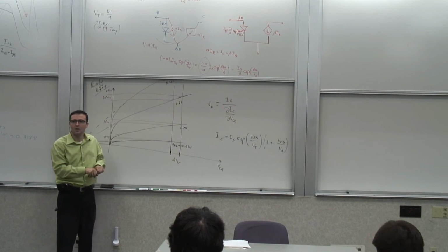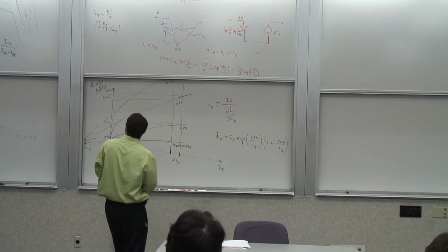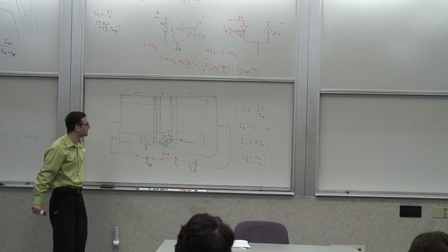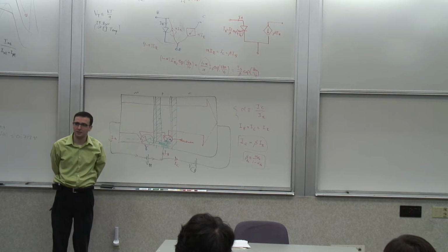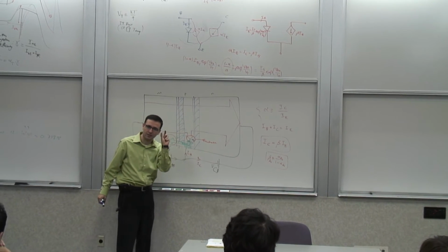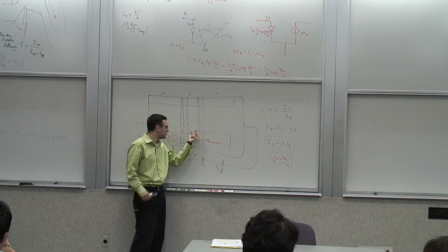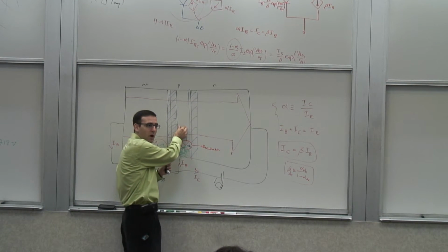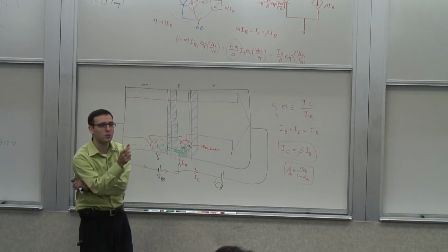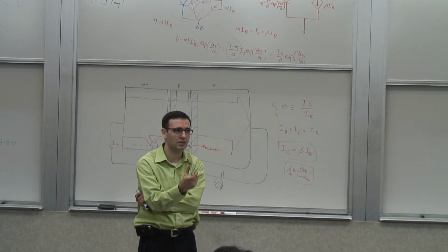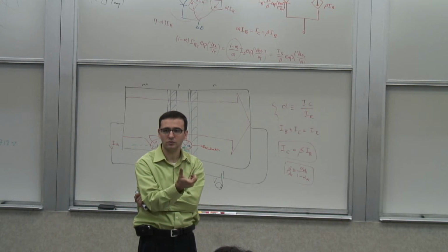Now, well, we are engineers, right? So we say, that's what we want. So what do we do to the transistor? Can we do something to the transistor to improve that? Let's go back. Let's see if we can play with this transistor a little bit. Some of the parameters we can control. What is causing this effect? The modulation of the effective base width, right? Because as you apply a larger reverse bias voltage, this becomes wider, and the effective base width becomes smaller. I want this effect to be minimized. I want the variation in the base width to be minimized. What is causing these variations? The depletion region, right? I want the variations of the depletion region to be minimized, at least on the base side. What do I do?